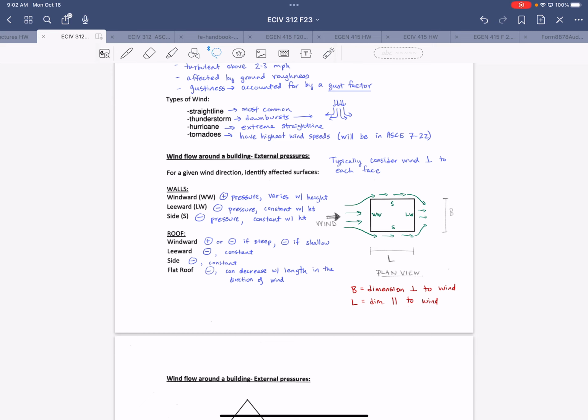Remember, for a truss, you have to change all of the members from rigid connect, which is the default setting, to simple connect. And that makes sure that we're modeling the truss as axial force only members that are pin connected to each other. But in order to make that model stable, after you make that change, you also have to restrain all of the nodes against rotation about Z. Otherwise, you'll get an unstable structure.